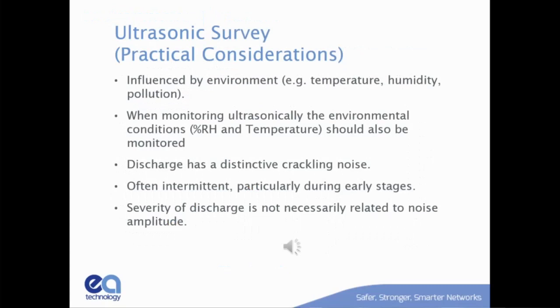So I don't know if you guys hear that sound, but that's the actual discharge recorded. Got a lot of 120 hertz component to it. So what it is at each voltage peak on the sine wave, which occurs 120 times a second, is a burst of 40 kilohertz noise, and that's what we're picking up, and then we're converting it down to 2 kilohertz center frequency so we can hear it. And that's really good because your ears are the most finely tuned instrument. You can listen to a singer sing the same song in concert and in the studio, and you can tell the difference. Your ears are incredibly fine-tuned instruments. And so that's one of the three primary methods we're going to use to determine the difference between noise and real discharge.